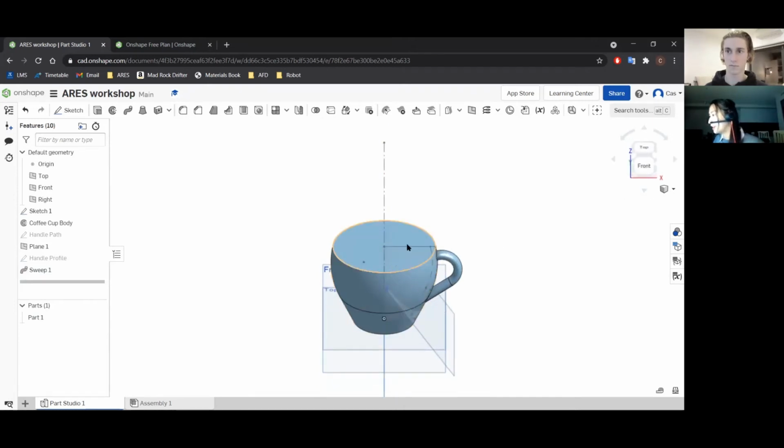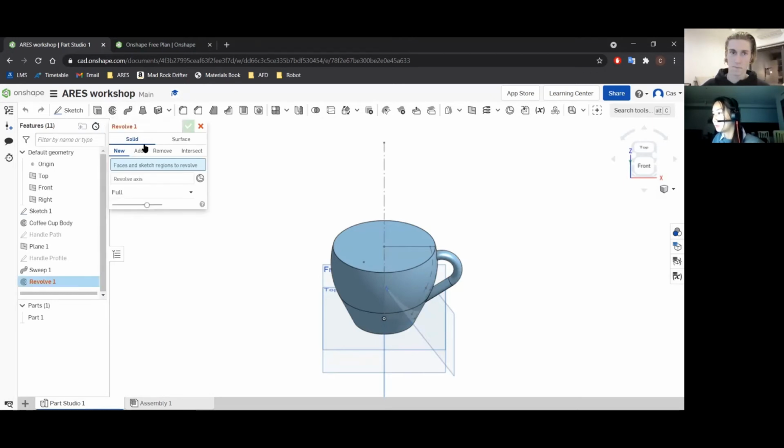Awesome, we're almost there. The only last thing is to make the hole in the center, right? Like I mentioned before, we just have to use the Revolve tool, but doing it using the negative side of it. So I'm going to click on revolve, I keep calling it Revolute. And instead of creating a new part, I'm going to remove stuff instead.